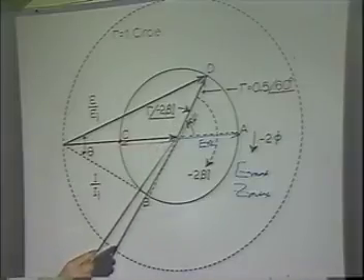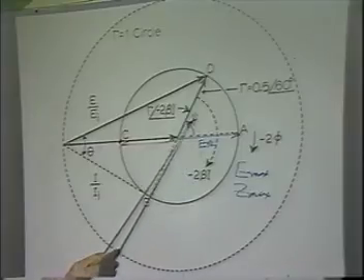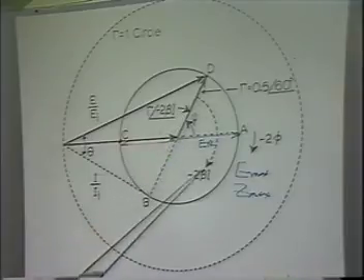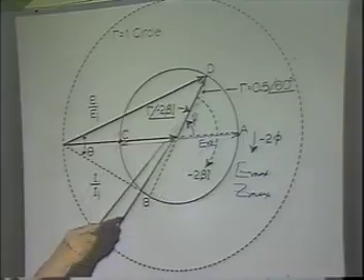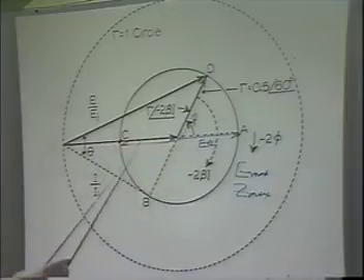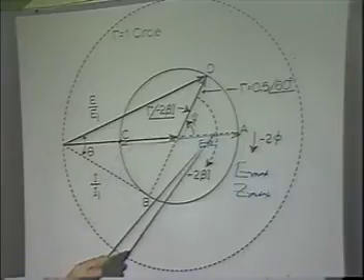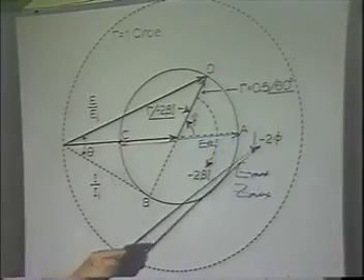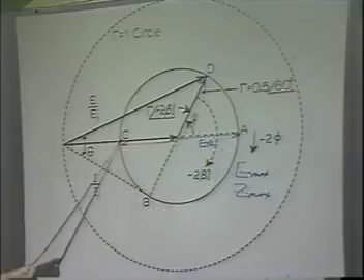I told you before that this angle here, when you subtract from this angle, this is the initial line. Notice this angle. It's just the angle of the reflection coefficient, right? If you subtract that from the angle of how far you travel around, suppose I traveled all around to this point here. Then if I subtract this angle from this angle all the way around to here, you can see that it's this angle plus 180, right? That's what you would actually see. It means that if you measured this angle here, you're always starting at A and traveling around here. How much is this angle? Well, if you subtract this one out, you're starting here. All the way around is 180 degrees.